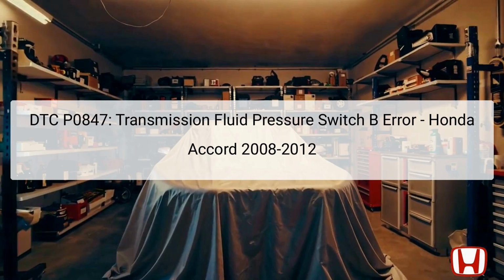The transmission fluid pressure switch plays a crucial role in monitoring the hydraulic pressure within the transmission system, which is vital for the proper functioning of the vehicle's automatic transmission. Located typically on the valve body of the transmission, this switch aids in regulating fluid flow and ensuring the correct application of clutches during gear shifts.